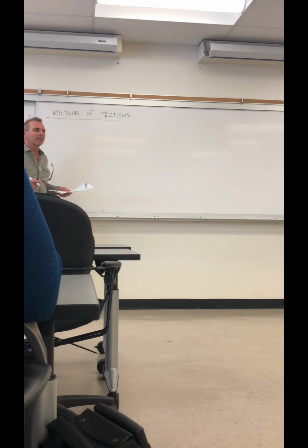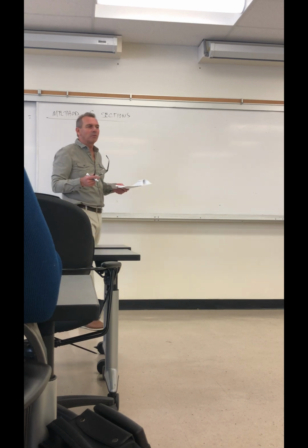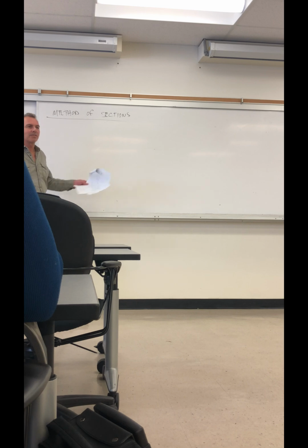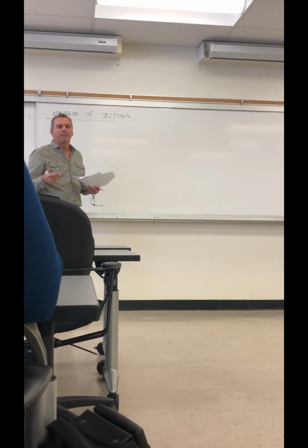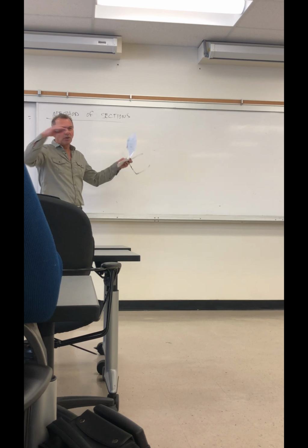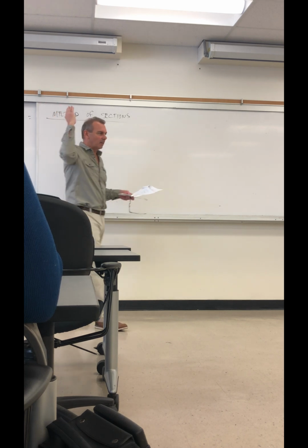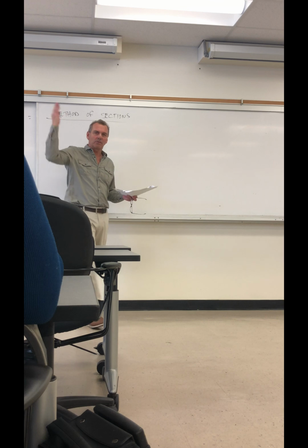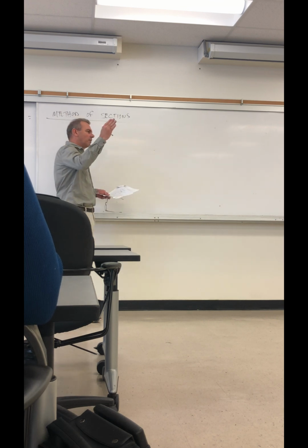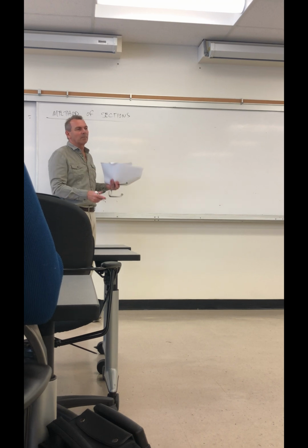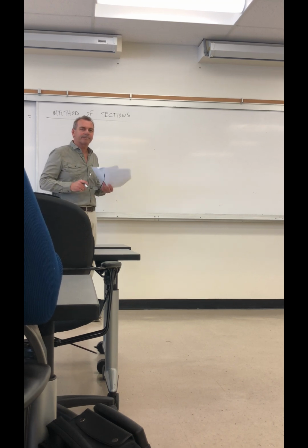Method of sections is, let's say you just want to solve for 2 or 3, way out in the middle of a truss. We don't want to take 5 hours to get there to solve for everything. Method of sections allows you to do that. We can just apply the loads on the truss, solve for the reactions like we did before, and then take an imaginary cut somewhere out in the middle of the structure, right through the structure. And every member that we cut through is a member we can solve for the forces directly by taking the section cut.